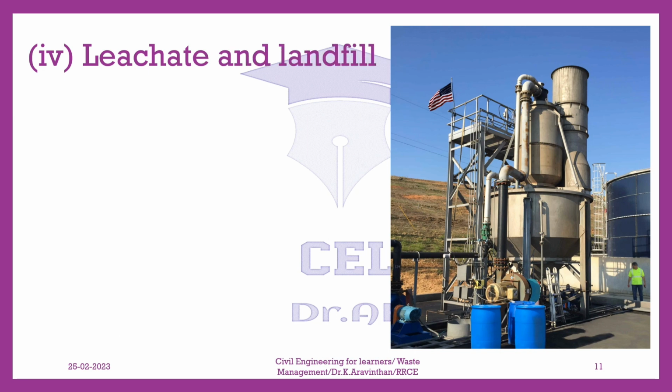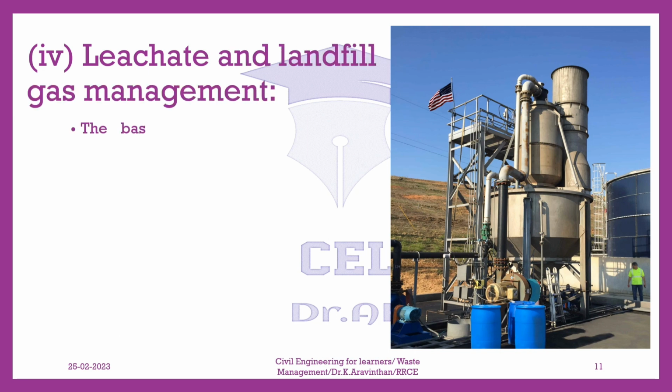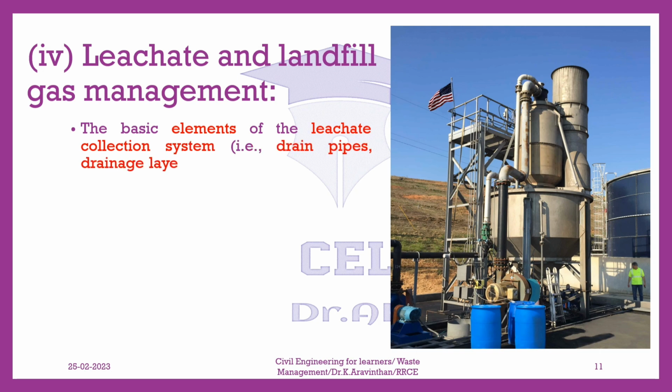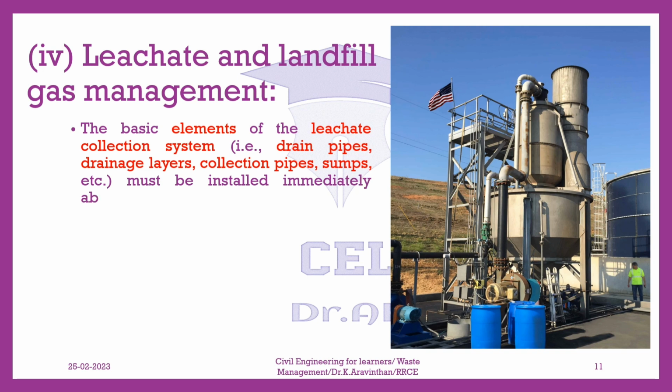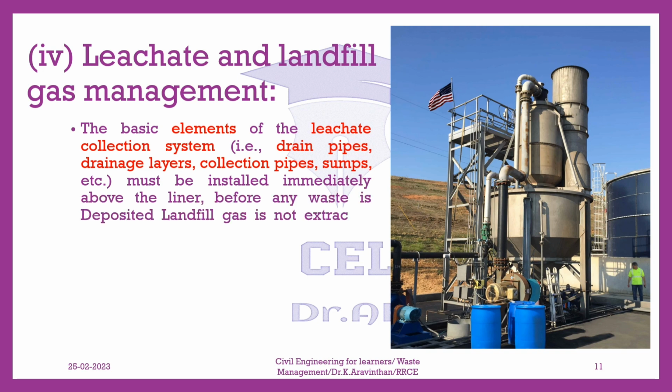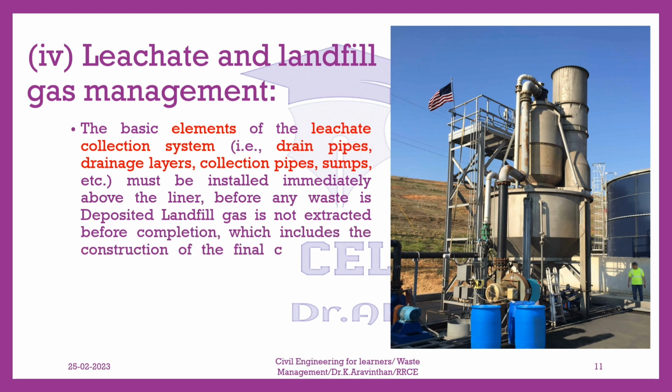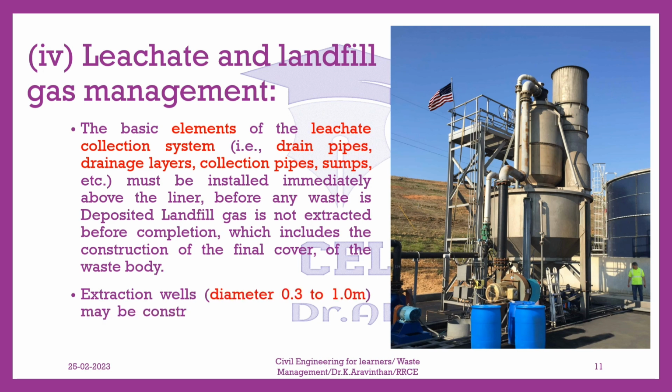4. Leachate and landfill gas management. The basic elements of the leachate collection system, drain pipes, drainage layers, collection pipes, sumps, etc., must be installed immediately above the liner before any waste is deposited. Landfill gas is not extracted before completion, which includes the construction of the final cover of the waste body. Extraction wells, diameter 0.3 to 1.0 m, may be constructed during or after the operation.